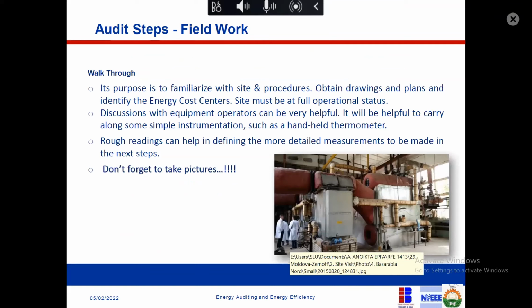Okay, you move to the field work. During your field work, don't forget to take pictures. There are some things you will not see. If you glance through the pictures, it may warrant you to go back to the site. Kim has showed us about the temperature gun. That temperature gun, if you shoot it at your electrical appliances, you can detect where there is too much resistance, and that will lead to losses.